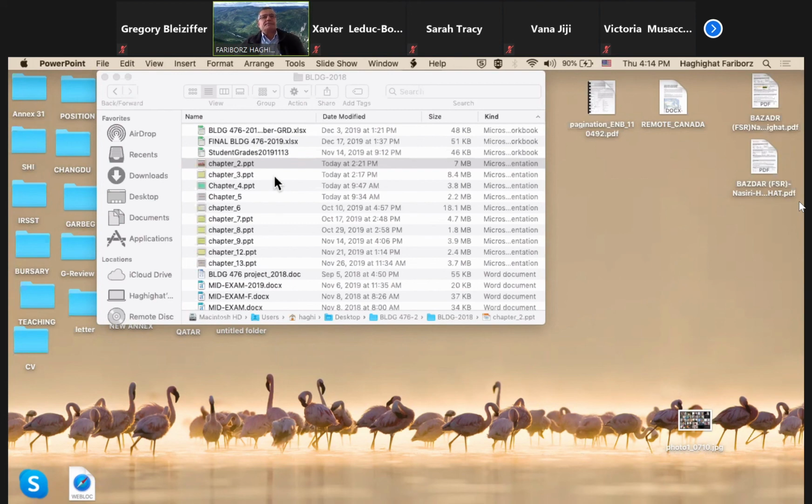Any other question? Sir, for the floor question, do we need to include the application of the shape factors? I have no idea why shape factor. Why your shape factor? Because you're writing in numerical, my friend. You know the resistance to the soil. You know the resistance to the convection. Why would you like to consider shape factor? Because you have the floor, and conduction comes through the floor soil. Therefore, you have k, thickness of the earth, temperature difference, times the area of the floor.